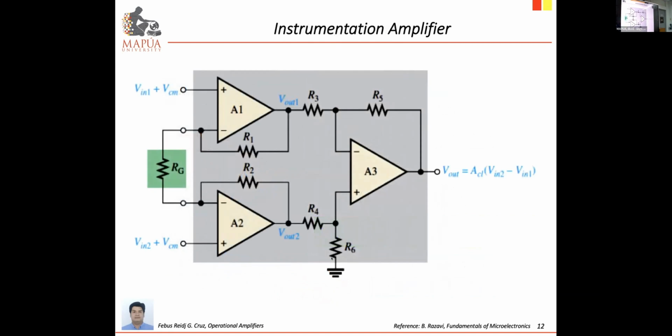All right, what about the exam? All right, so the approach, whenever you have cascaded or multiple op amps in one circuit, all you have to do is analyze it one at a time. All right, since each of the op amps has an open circuit input, it doesn't matter on the input or previous stages.